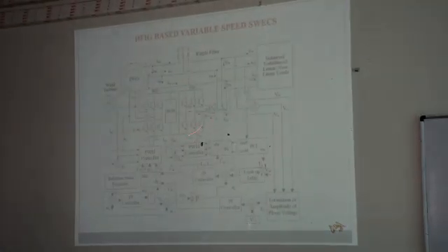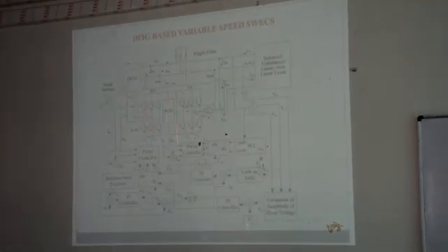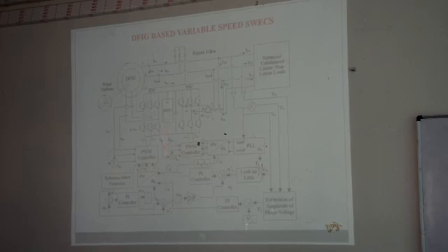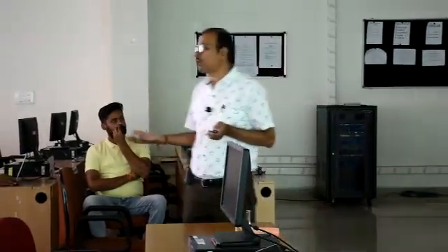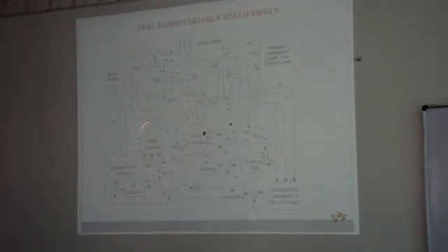And because now the DC link is coming between these two converters which are at the rotor side, the battery energy storage is coming here. Sometimes people have used this energy storage system with the help of another converter, which is a DC to DC converter. What advantage will you get there? Here I have to use a battery of high voltage, but managing the battery at a little bit high voltage is difficult. So what will people do? They will use a buck boost converter at this point. They will take a battery of 24 volt or 48 volt and interface it with this DC link.